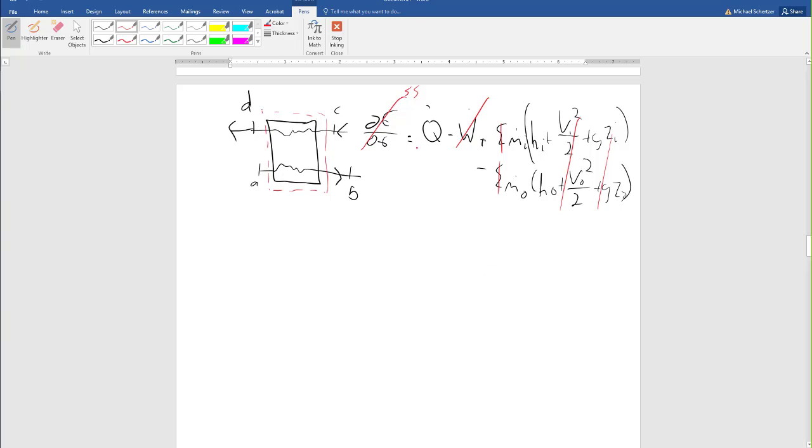And then we'll normally say that it's adiabatic. What that means is that all the heat from the hot side goes into the cold side, that none of it escapes to the atmosphere. If this is what we get, then 0 is equal to the sum of m dot in, h in, minus the sum of m dot out, h out.